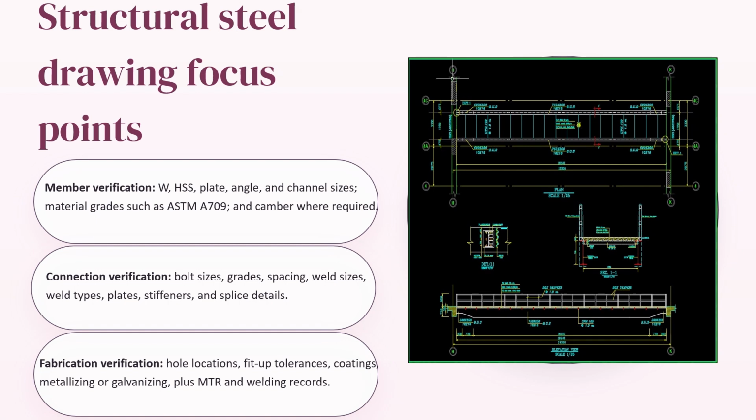The certifications might include MTRs, bolt certifications, WPS or PQR, welder qualifications and coating certifications. You need to check the spec. What are the certifications that are required for this structural steel shop drawing?